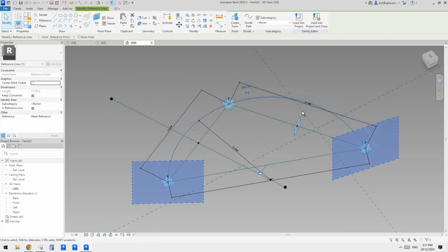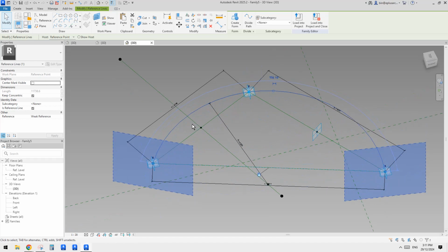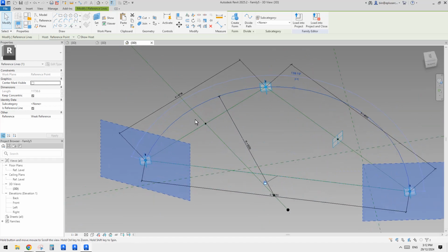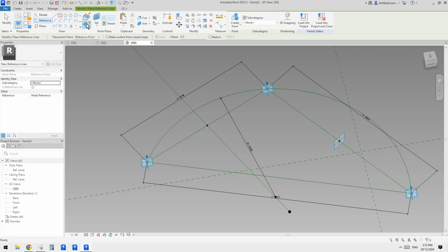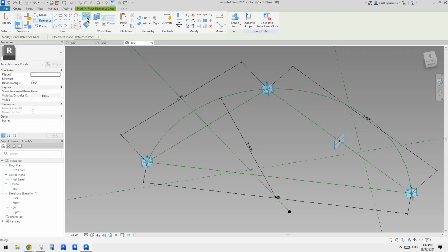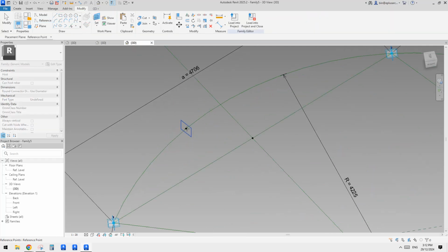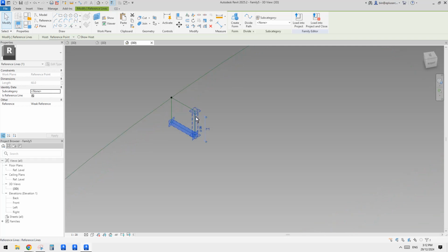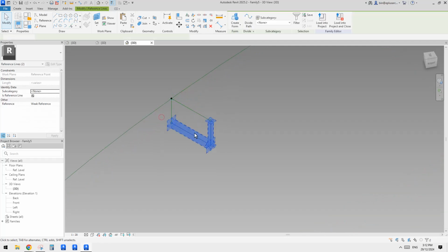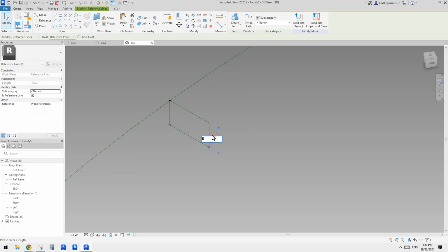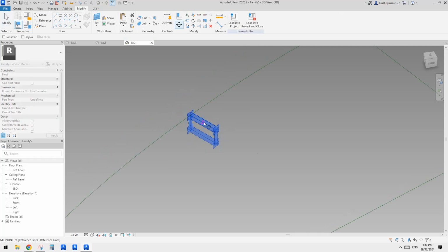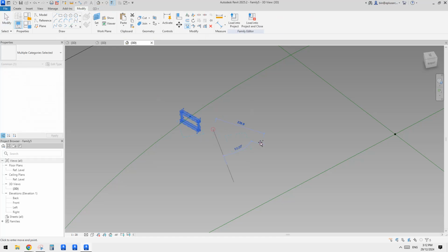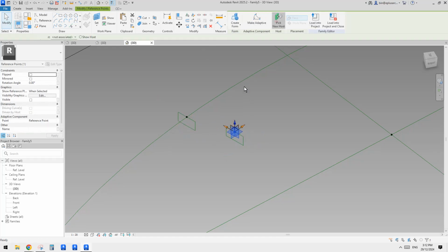So now we have this arc, and then we can create something onto it. Right. So let's just quickly do it. First we need a point, draw on face, and do a profile, draw on world plane profile. I'll do it very quickly because we've already done this before, so I'm not going to do it again. So 50 by 100 and move it. Okay, and select them, CC, and pick new host.